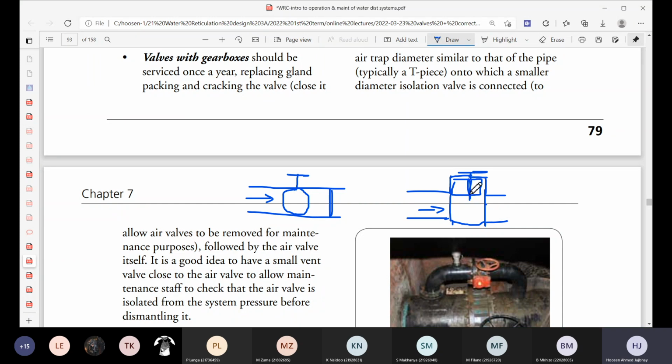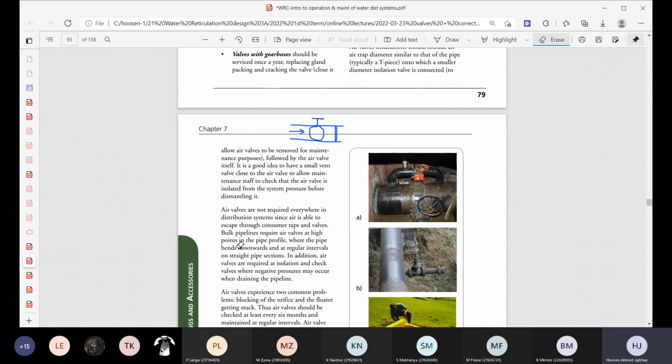When it's open, it'll be in the up position like that, and when it's closed, it'll shut off flow and come into the bottom position like that. So you have a plate that moves up and down over there. There are lots of other details that go with it, but it gives you the idea of how it operates. So that's how a gate valve operates. It's like a sluice that moves up and down within the valve itself to open flow and cut off flow.